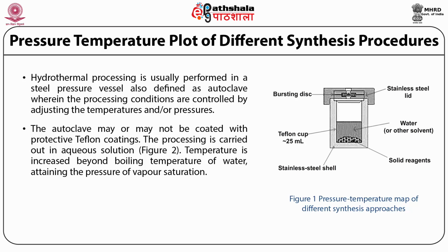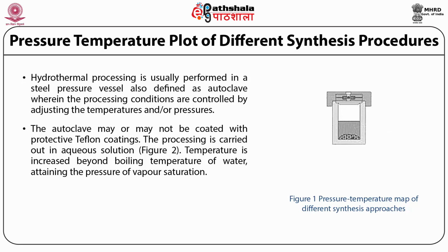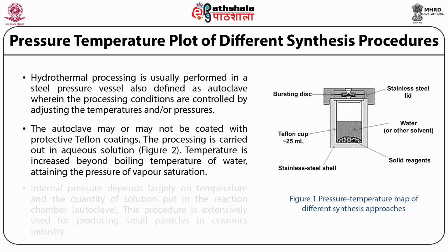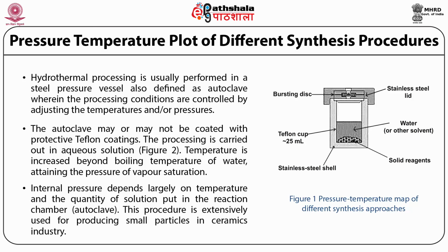The temperature is increased beyond boiling temperature of water, attaining the pressure of vapor saturation. Internal pressure depends largely on temperature and the quantity of solution which is put inside the reaction chamber, that is autoclave. This procedure is extensively used for producing small particles in ceramics industry.